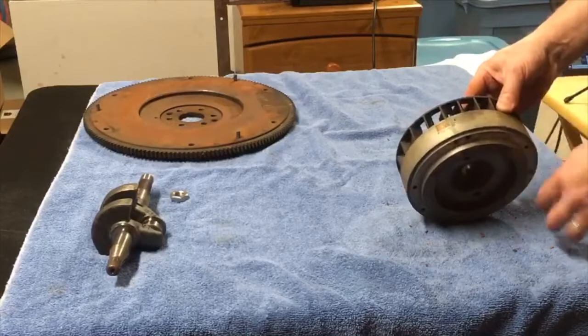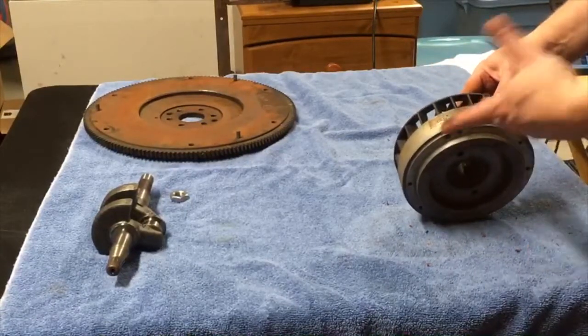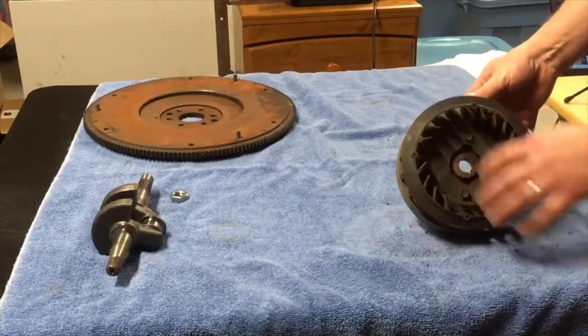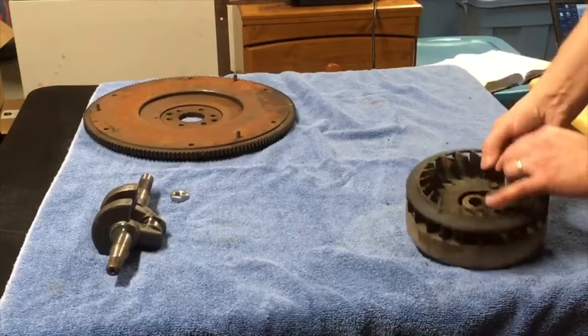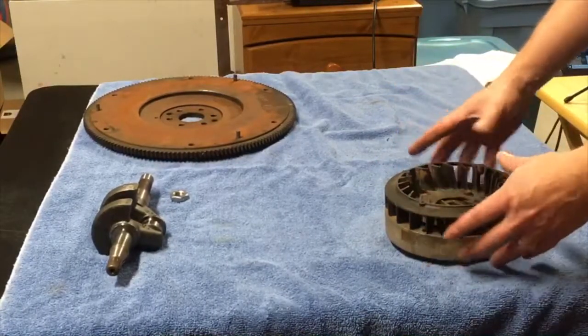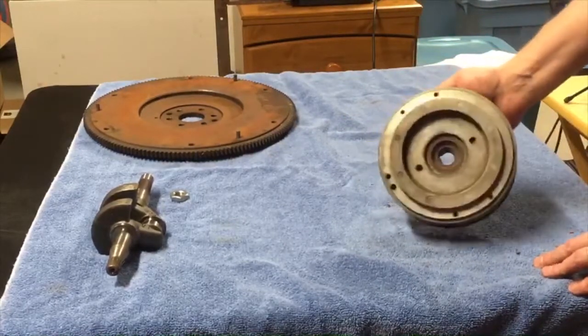And as the flywheel spins, it triggers the coil, which creates a spark that goes to the spark plug, and that's your ignition point. Anyway, this has got a plastic fan that's bolted to the flywheel. On the engine, in stock trim anyway, there would be a fan housing, and this fan blows air across the motor because it's an air-cooled application.